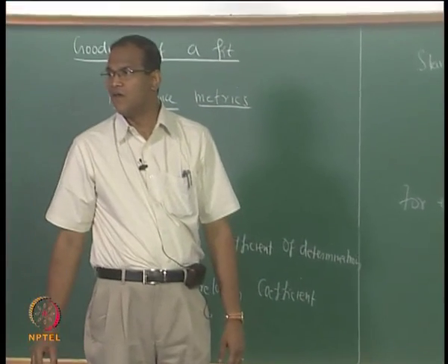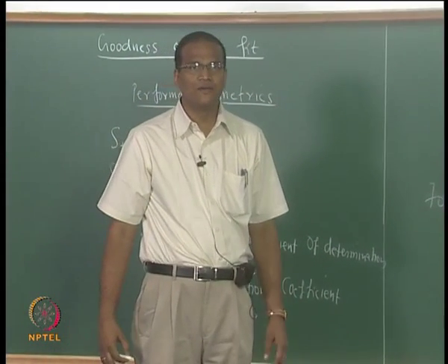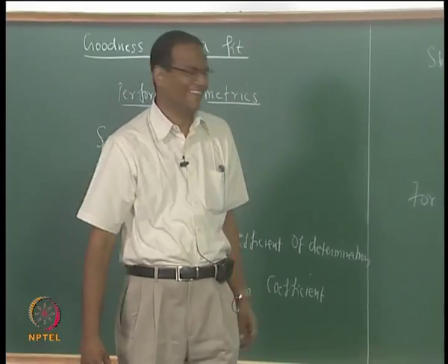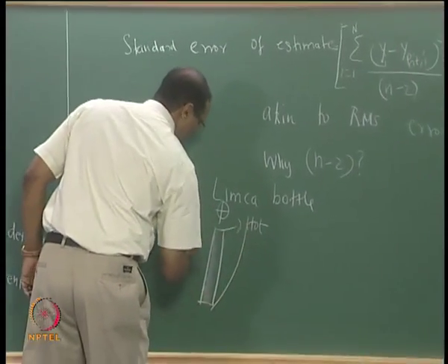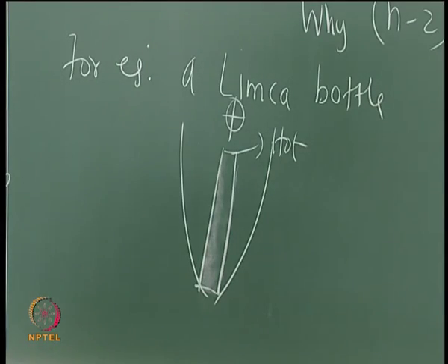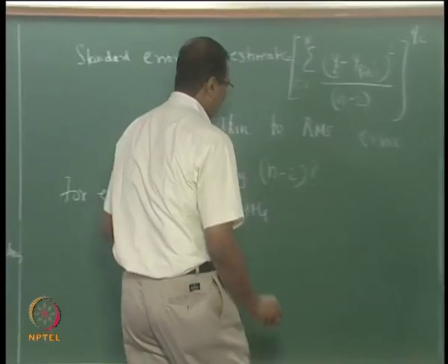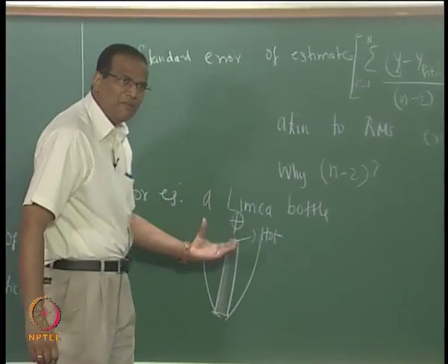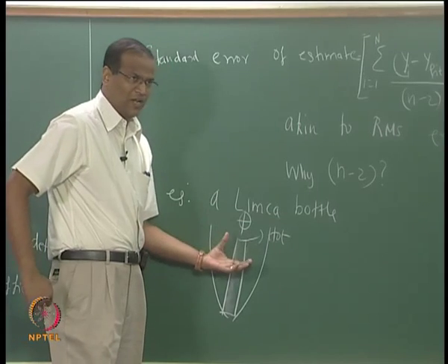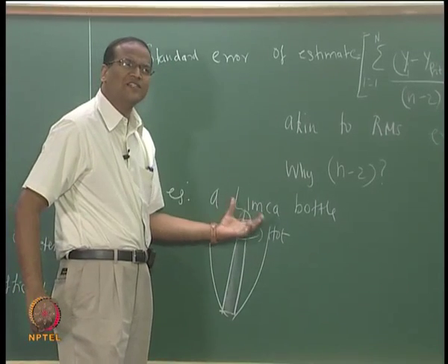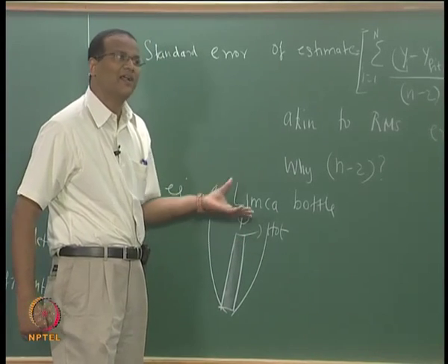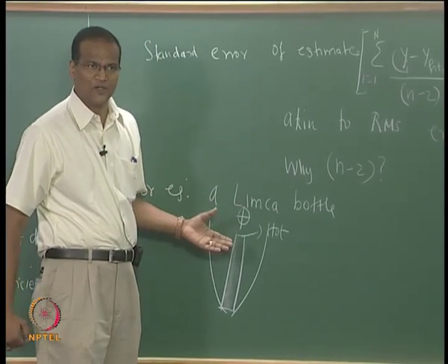Natural convection boundary layer, how will it develop? It will develop like this, right? What will happen is that this boundary layer is actually an impediment to the heat transfer. The heat transfer coefficient is inversely proportional to the thickness. So if you are somehow able to get the average thickness of the boundary layer, the heat transfer coefficient is inversely proportional to the average thickness.